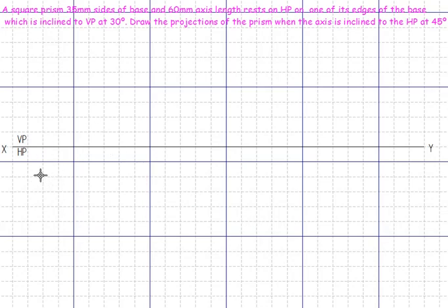It can be from any distance. So start it from the third box. The other box is for giving the dimensions. I'll keep here this length equal to 35, and from here 35, then here 35 and 35. The top view is going to be drawn in thick lines. As soon as you draw any polygon, give its dimensions. The distance from this edge to the dimension line should be 10 mm.